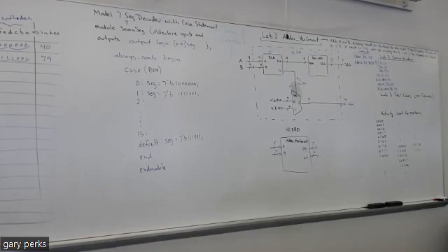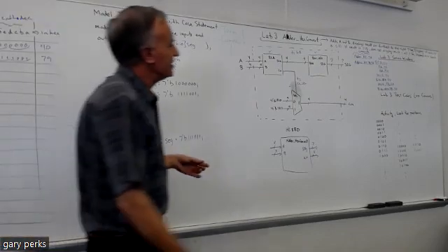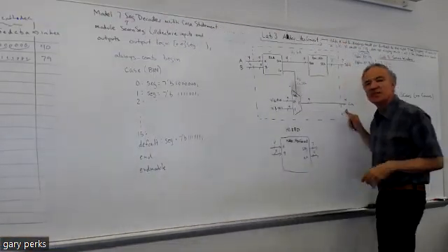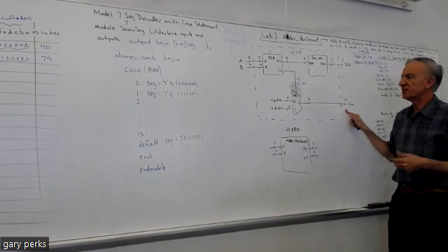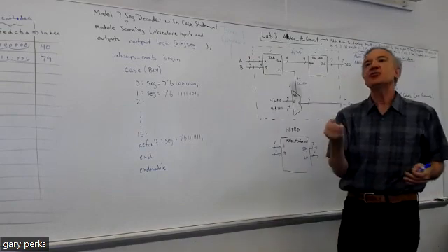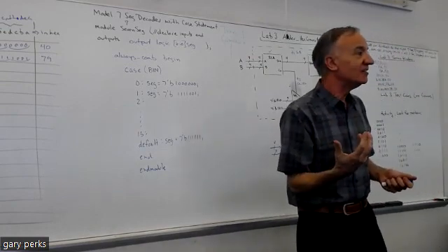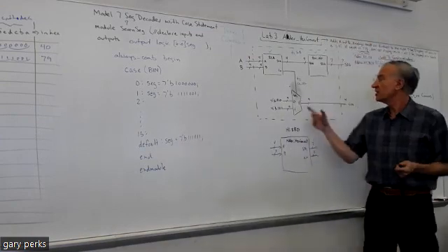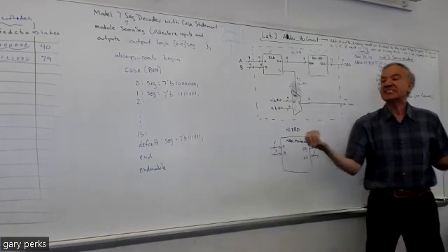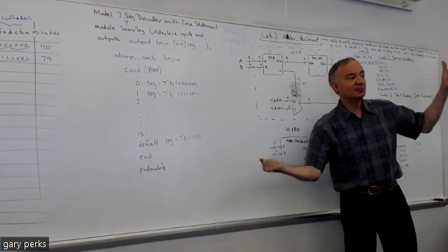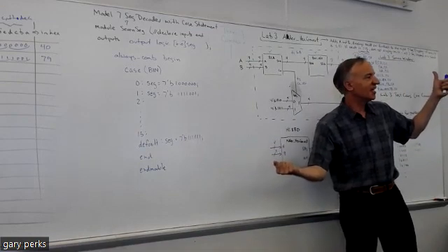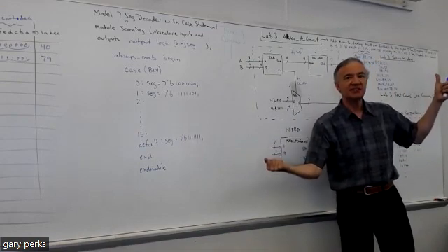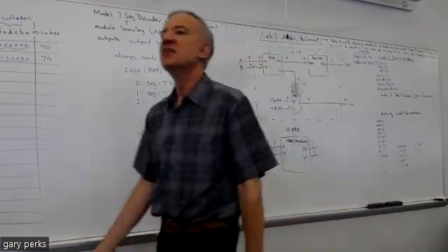No, I can't light it. So you see, one way to think of this anode output to the 7-segment display is that it controls whether the display is going to light at all. Where the seg bits determine which segment lights as long as the display has the ability to light. You have a question?